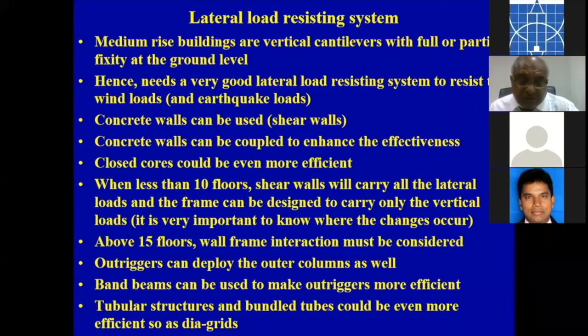So this is called risk assessment. For every element, when you are designing, you will not only look at the bending moment, you will look at whether this bending moment changes over the lifespan of the building. If the bending moment can change, then you have to include that change in your design. For example, when you design the building, you will model the foundation, then car park levels, then the transfer plate, and then the building above the transfer plate.